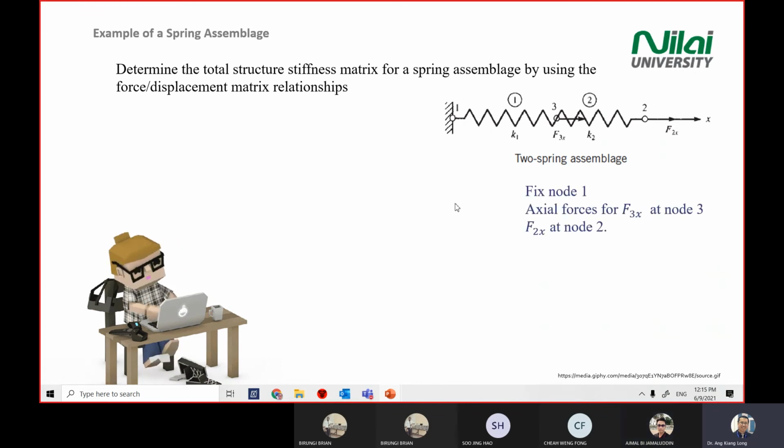So we continue with the discussion for this question. If you look at the diagram, you see this symbol at point 1, a line and a slanted line, which means that point 1 cannot move. It's a fixed point. If you are using ANSYS software or other simulation software, when you do the boundary condition setting, point 1 cannot move.